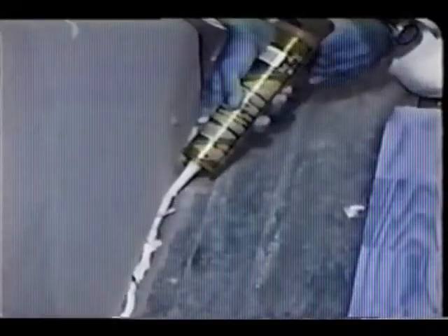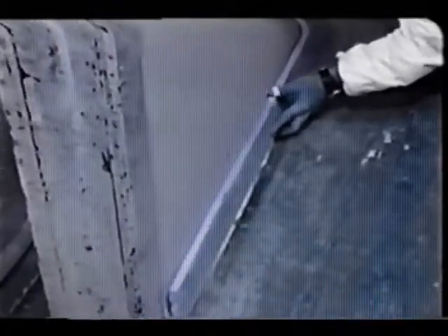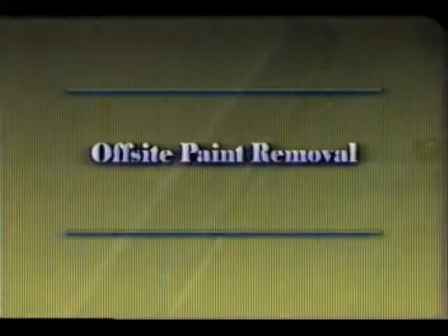The drywall should be glued, screwed, and finished through standard construction practices. All edges and seams should be sealed with caulk or other sealant. Enclosures are intended to prevent access and exposure to lead-based painted surfaces and provide a dust-tight system to trap any lead-contaminated dust.